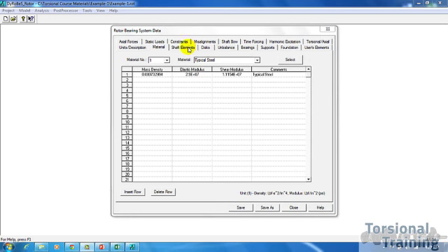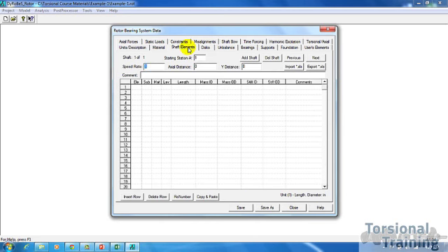And after selecting the material, go ahead and now click on shaft elements, and this here is the meat and potatoes of Dyrobes. This is where you build your rotor. Dyrobes follows a sort of finite element approach. If you've had any experience modeling using ANSYS, then think about what you do. You select your units, you select your materials, and then you do your pre-processing, build your model, and then you assign your elements.